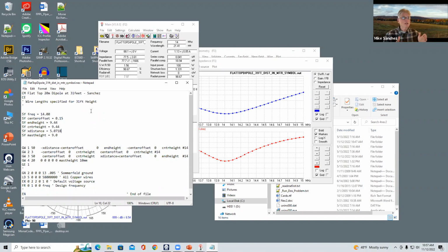So instead of using 468, cutting, and then raising and lowering, I built it above a 40 meter dipole, which had some interaction. So I put them both into the simulation at the right geometry and the right distances, and I ran both of them. It's interesting because the 40 meter dipole does affect the length as opposed to it just sitting out there by itself.